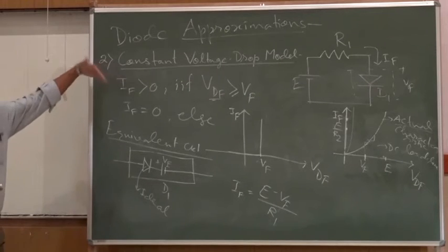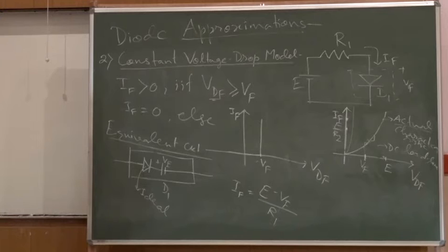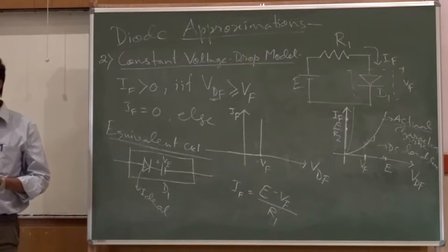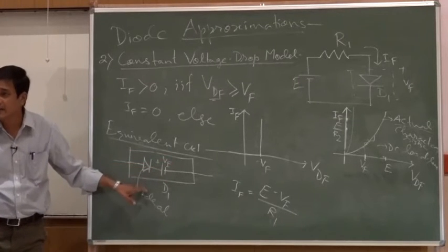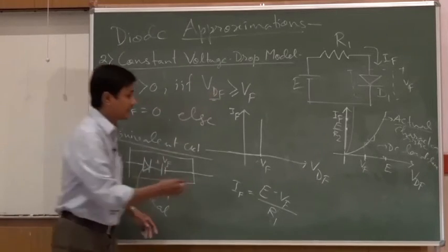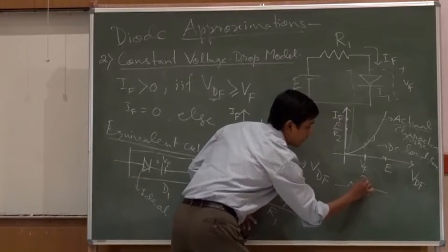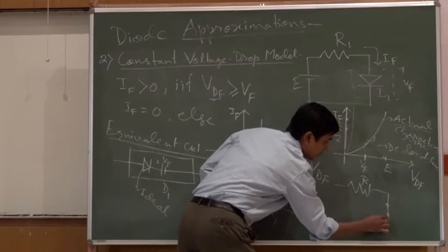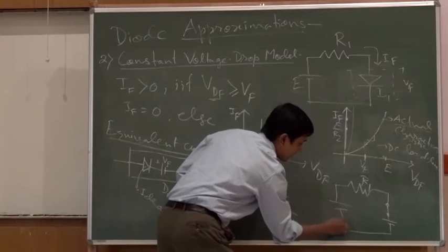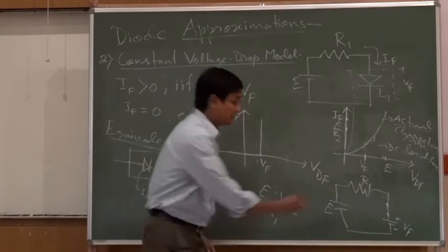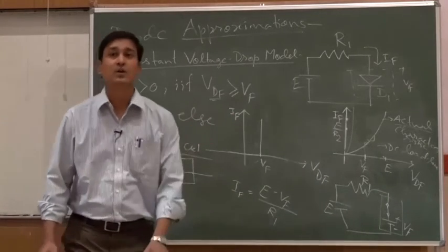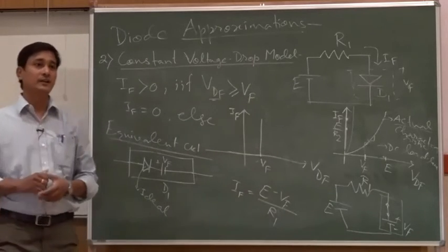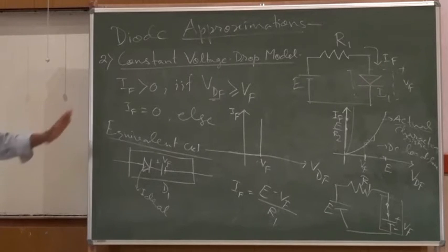Okay? So, we will go for another model which may be much more accurate in terms of the actual characteristics of the diode. Now, one thing you should not miss here is that I am representing this electrical circuit in terms of an ideal diode, where after I see that things are getting conducted here, this electrical circuit will be considered as R1, then it is short, then one potential drop has come as plus minus Vf. This is the diode. Okay. So, things are represented in terms of the ideal one, because we always need somebody with reference to which the remaining things will be defined. For that only this ideal part has come into it. Okay. So, let us move to another model.